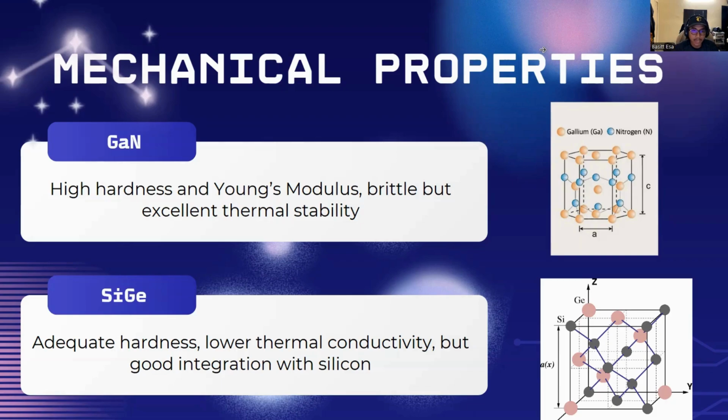Despite being at the distant end of the scale for hardness, GaN is relatively brittle compared to other microstructural materials, having low fracture toughness of 1.5 to 2.5 MPa·m^0.5. However, this is compensated with very high thermal conductivity, which is essential for getting rid of vast amounts of excess heat developed due to the high power effect, aiding the device in not getting destroyed due to overheating, so it can perform adequately within its working environment. GaN's high thermal stability and piezoelectric constants make it suitable for various applications.